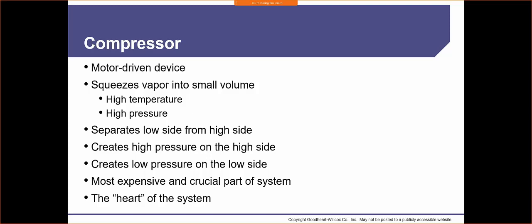We put a vacuum on our system. We suck out, or not suck out, well, partially, we suck out any impurities that are in the system. We also drop the pressure into a vacuum state. By doing so, we cause the moisture to evaporate, so we don't have that 212 degree boiling point anymore of water. We've got a sub-zero boiling point of water, and everything is just going to naturally boil out. We'll have a nice clean system where we can release the refrigerant and have less chance of a burnout.